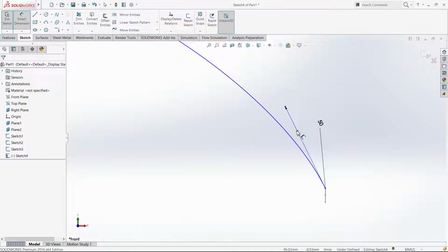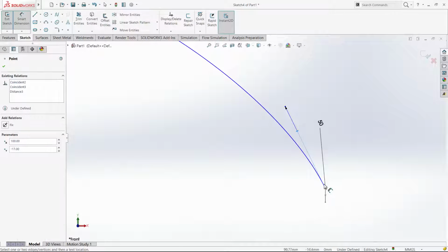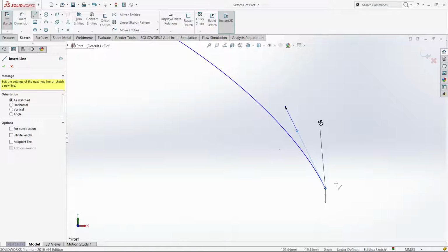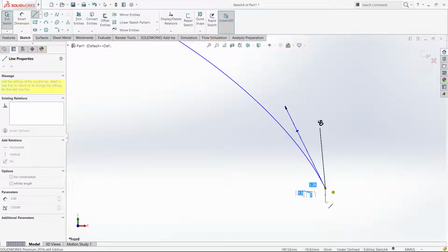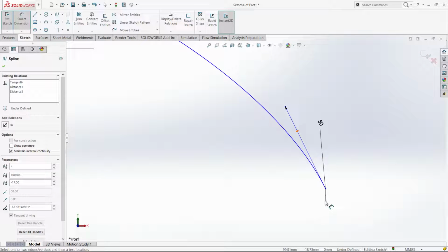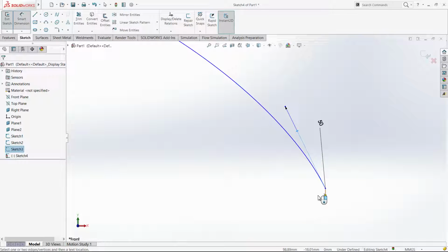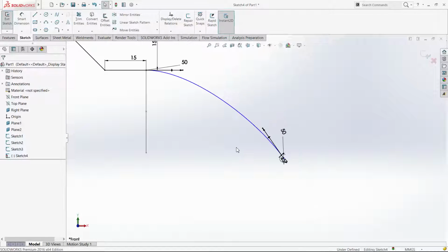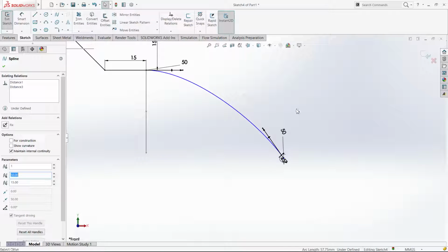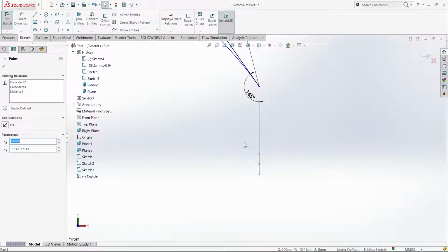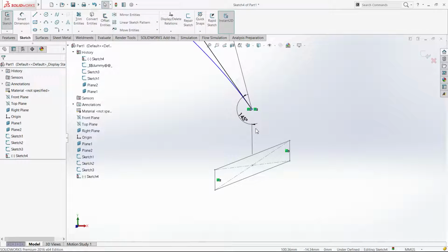Okay, smart dimension there, 9.9. No. Okay, so I just wanted to create an angle there, but seems like it wouldn't let me. So I'm gonna go with smart dimension 0.9, and I can have my little shape there. And as an end result, I also need to do the same thing as I did last time, which is pierce.